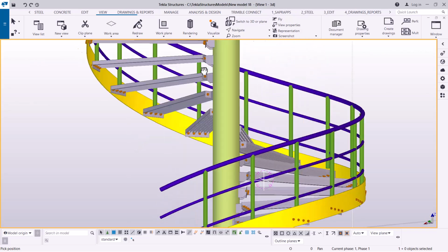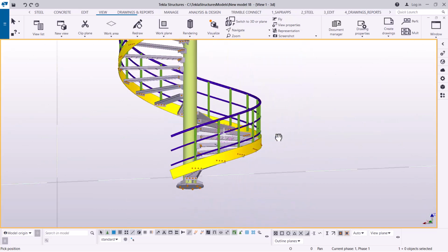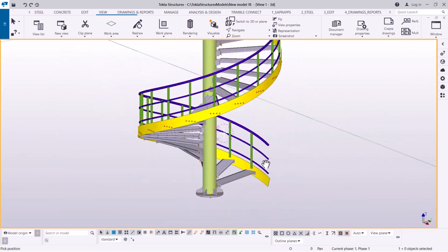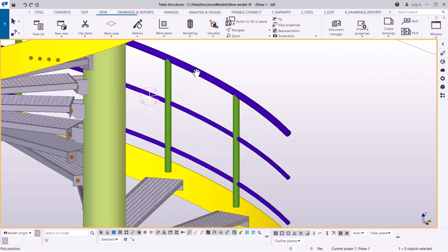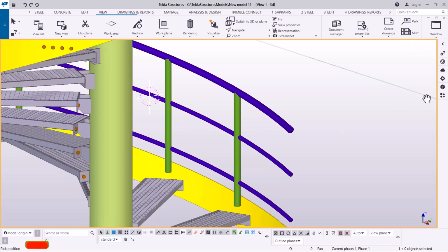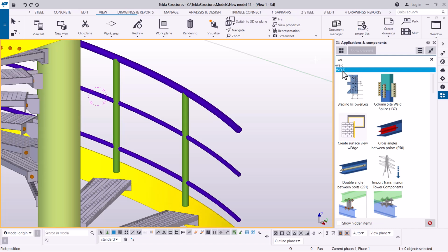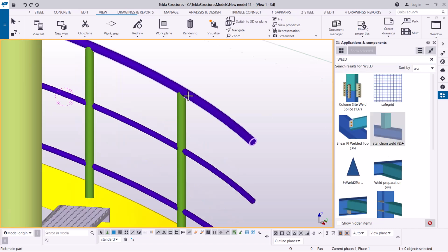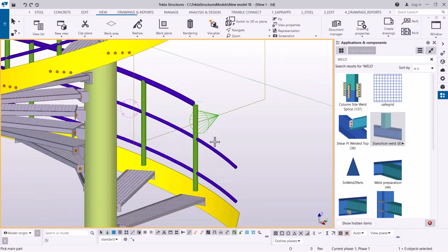So I hope we've gotten something, and I think we'll terminate our presentation on that spot. I'll leave it for you to find a way on how you can trim this, though there are so many ways. You can just weld. You can click here, weld this to this, weld this to this. Let me just show you one trick here. You can come here and maybe weld. Let me just type weld there, and I'll pick that member, and I want to weld this to that. Let's see how it will behave, and we've welded that to that.